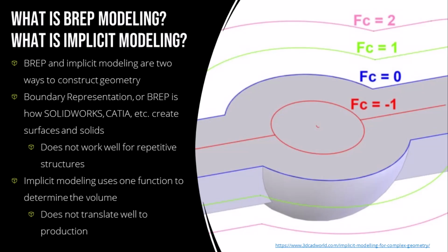If you've taken our surface modeling class, you'll know that solids are composed of knit-together surfaces to create fully enclosed volumes. Implicit modeling, instead of using a formula for every single edge and surface in a solid, uses a single formula to define the entire volume in space. Pure implicit modeling generally utilizes what are called primitives. Usually a cube, sphere, cylinder, or cone are used with Boolean operations to create a part.